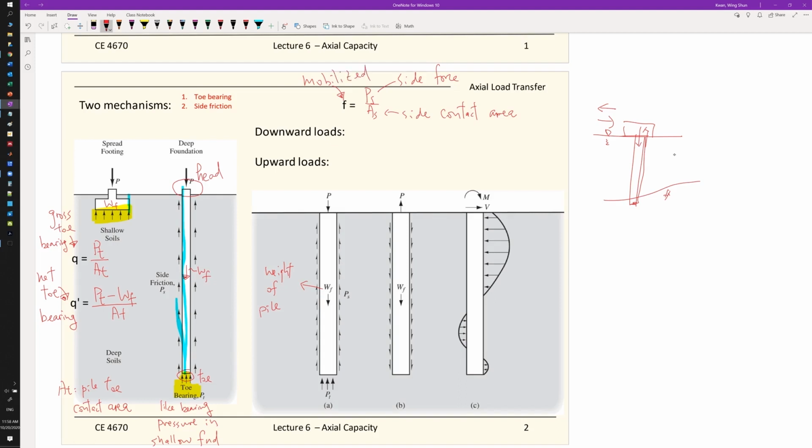So when you think about soil behavior, again, you need to think about a stress strain curve. So does the structural soil interactions between the piles and the soils. The performance, the strength or the capacity that you gain from the soil strength, it just depends on the displacements, how much soil you have mobilized. So this is the mobilized side friction.